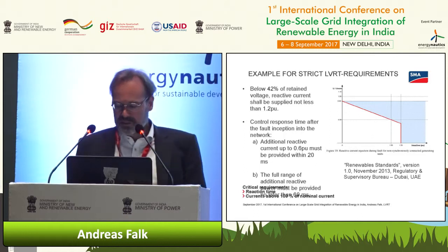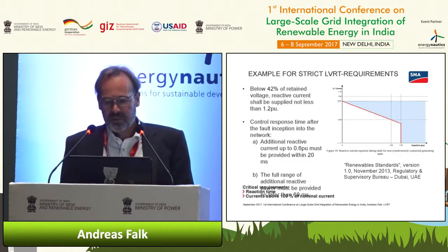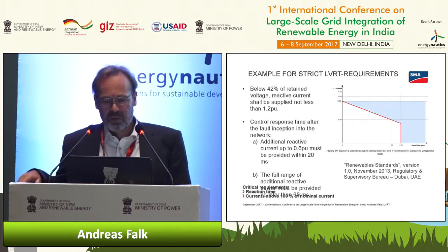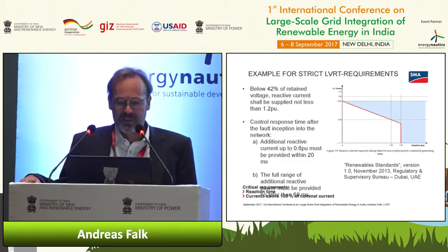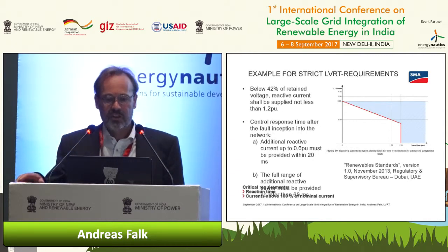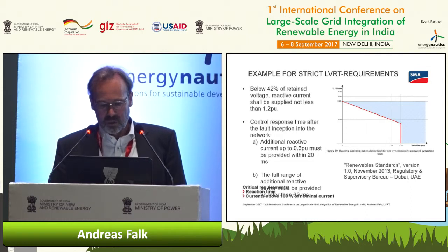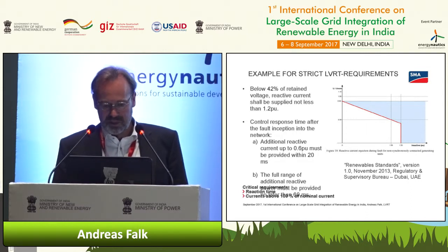And that's not all. They are requiring 50% of this 120% injected within 20 milliseconds, and the full range of additional reactive power has to be provided within 60 milliseconds.